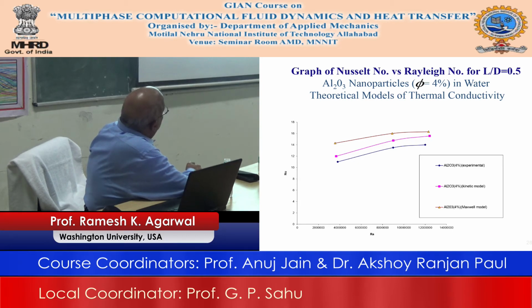So now you see that this is the Nusselt number of pure water again, but now L over D is 1. So the aspect ratio is larger, which means there is a lot more room for the heat to transfer in the buoyant fashion. And then again, this is 1%. You can see the difference between the calculation and the experiment, calculation is always in red.